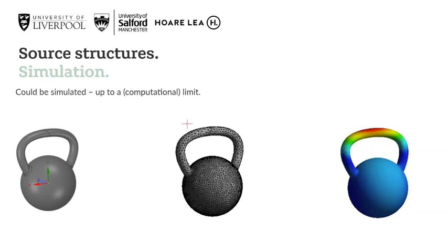There are, however, disadvantages. Firstly, we need the software, which doesn't come cheap, and the simulation procedure, much like the measurement, requires certain protocols to ensure that we don't end up in a rubbish in, rubbish out type situation. Further to this, the computational effort to capture a broad range of frequencies or mesh densities to resolve large complex geometries can also be significant, and runtimes aren't quick. They can take hours, days, or weeks in extreme cases.